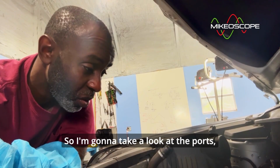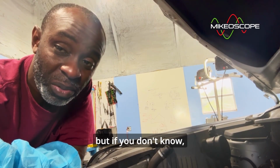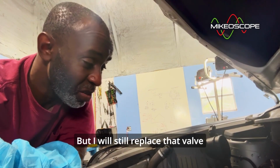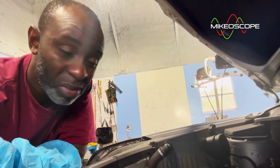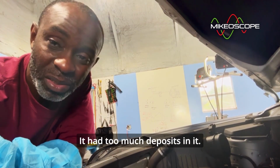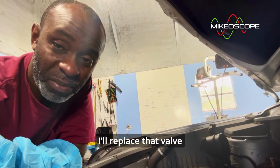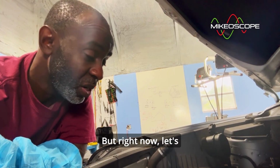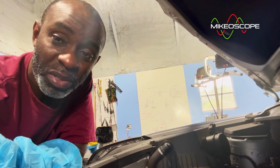So I'm going to take a look at the ports, but if you don't know, there's a TSB out for this. But I will still replace that valve because it looked too bad, and I don't really want to take chances with it. I'll replace it anyway. The one on the right-hand side, it had too much deposits in it. So after cleaning the ports, I'll replace that valve and we'll see what we get. But right now, let's go take out the adapter and then we'll take a look at the SAI ports.